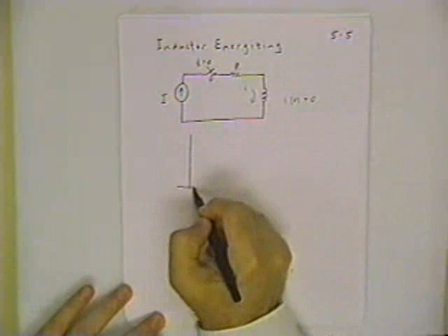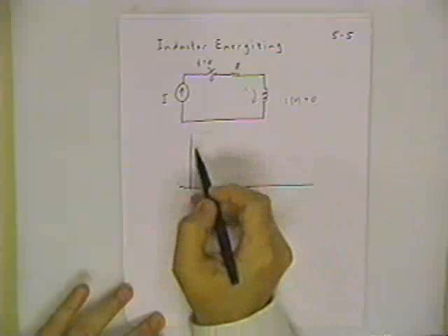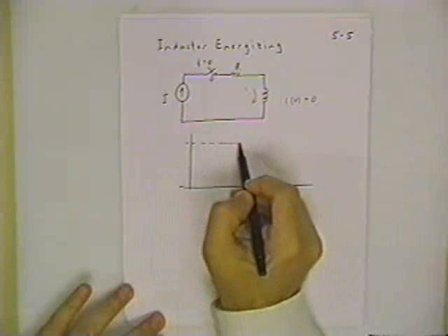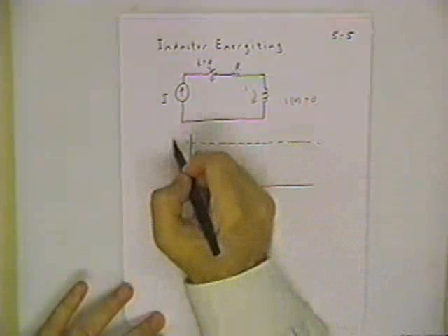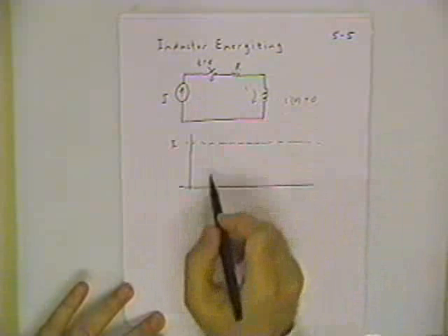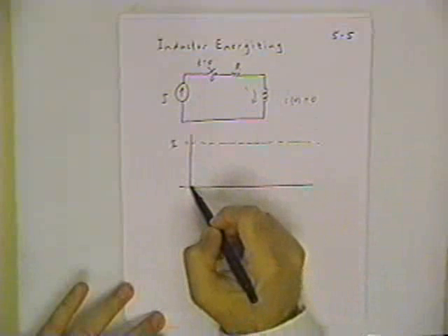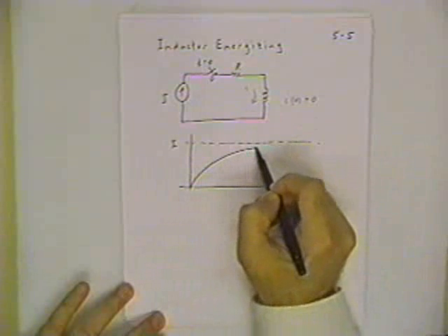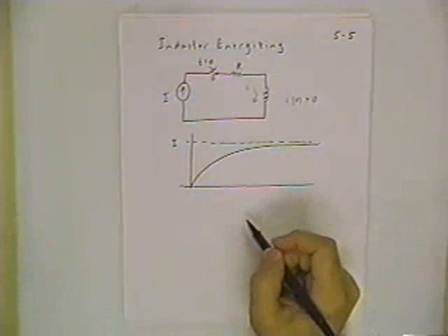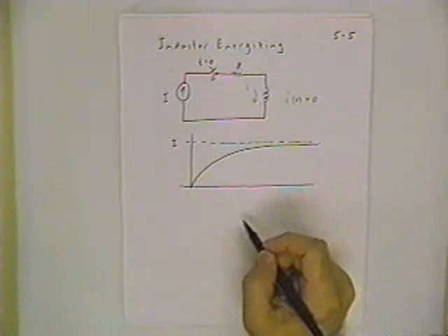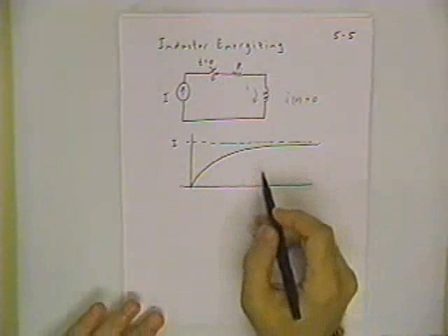So, just appealing to your intuition now, what we have is a capacitor charging situation to think back to. This inductor, energizing up to a full current of I, is going to follow the same basic physics, because after all, the basic VI equations are the same, derivative of one relating to the value of the other.